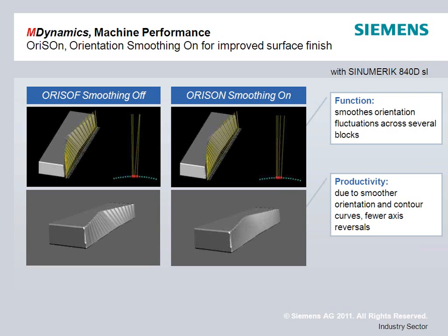But what will end up happening is that if you're swinging an 18-inch pivot length or so, by the time you multiply that out to 18 inches, you're asking your linear axes carrying that rotary to be moving around quite a bit and maybe making short, quick reversing moves, which is a very high dynamic load on those axes. By smoothing out the orientation, you also get a much faster program execution because we're no longer putting in those short reversal moves on your linear axes.